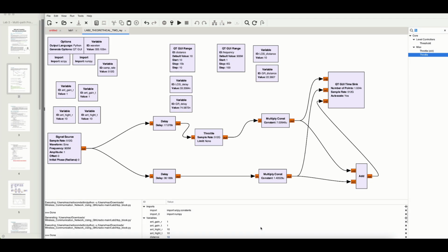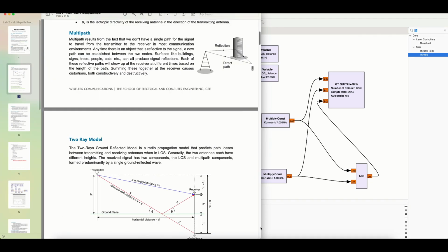The concept that we're about to discuss is basically known as multipath fading. As we know in wireless communication, when a signal is transmitted from your transmitter, at the receiving end you will get multiple copies of the same signal because the signal is being reflected, refracted, scattered, and things like that. You will get different signal strengths, and if they get added at the receiving end constructively, you will get an entire signal. If they get added destructively, you won't get any signal. This is what multipath fading is all about.